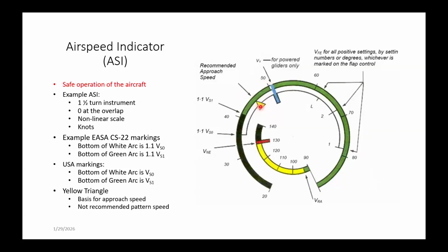This number is supposed to be at max landing weight. And what you have to do is check your aircraft's flight manual, because in some cases, the max landing weight does not include ballast. So you could have a takeoff weight, a max gross for takeoff at 525 kilos, but you've got to drop your ballast in order to be able to fly this. So check your flight manual to be sure what that triangle means for your aircraft and for the configuration that you're flying it. Okay.